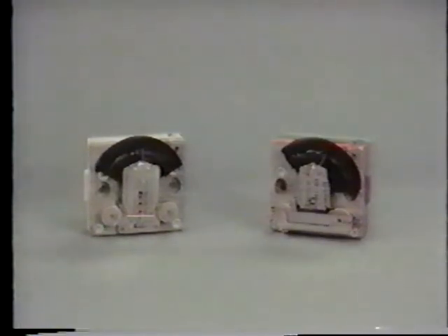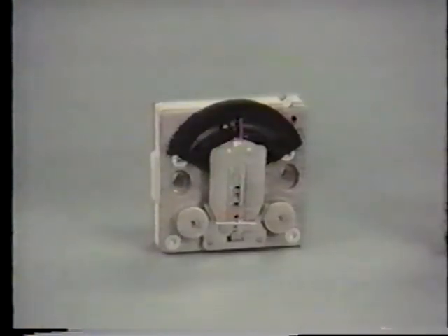The summer-winter thermostats come in two models: the single bimetal for the same set point, summer and winter, and a dual bimetal to accommodate different set points for summer and winter. This is the single bimetal summer-winter thermostat. Notice that this thermostat has only one bimetal and looks very much like the single pressure models. This is the energy conservation model summer-winter thermostat. Notice it's a dual bimetal model with two set point adjustments.